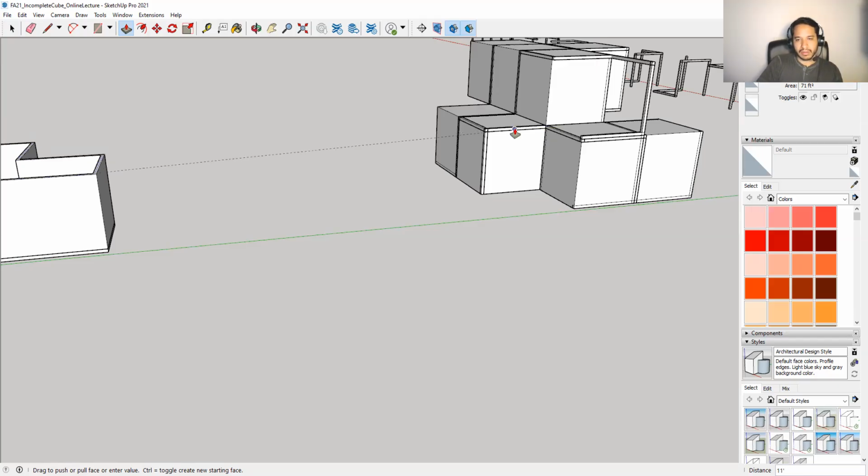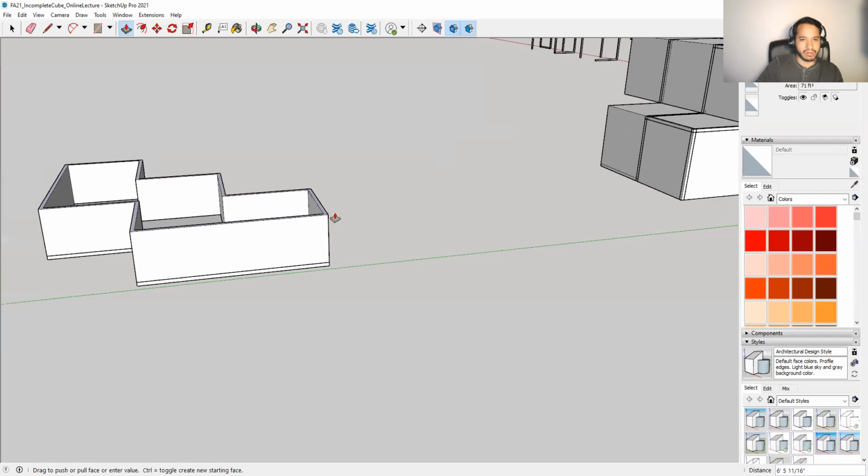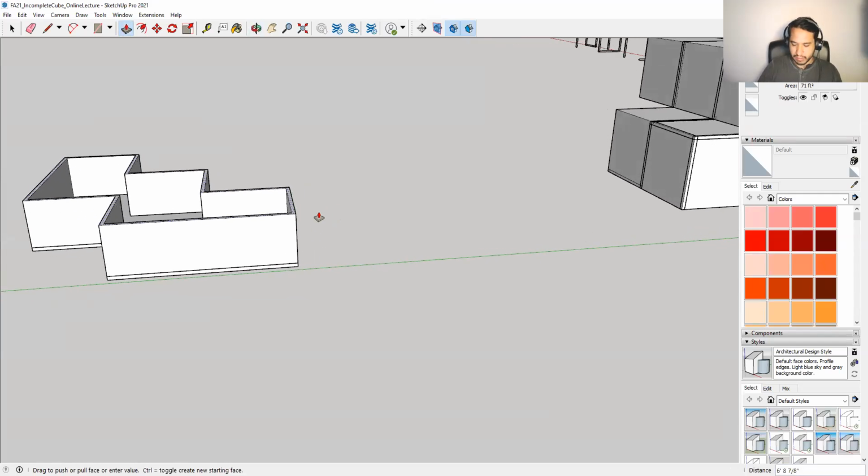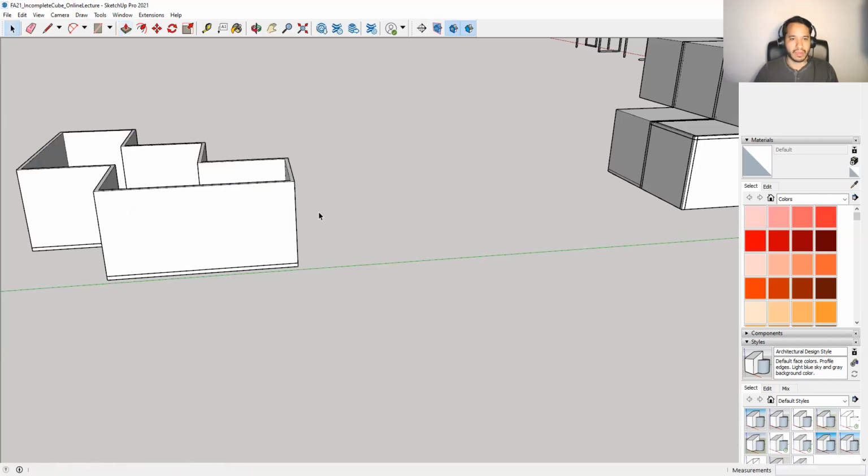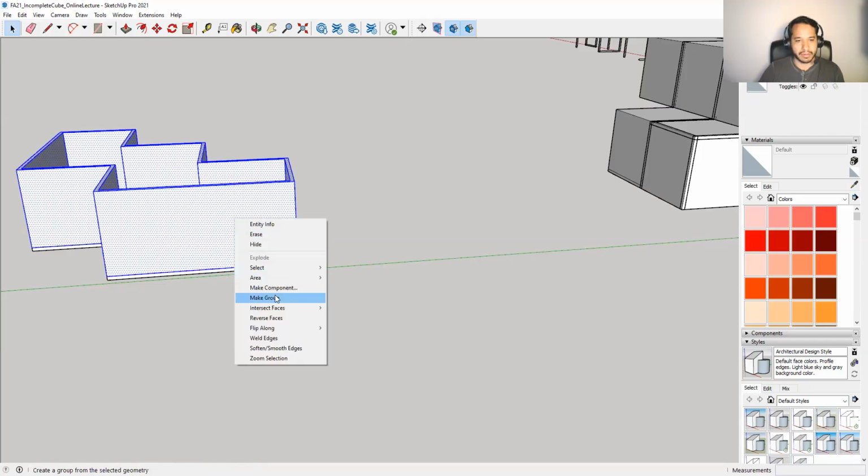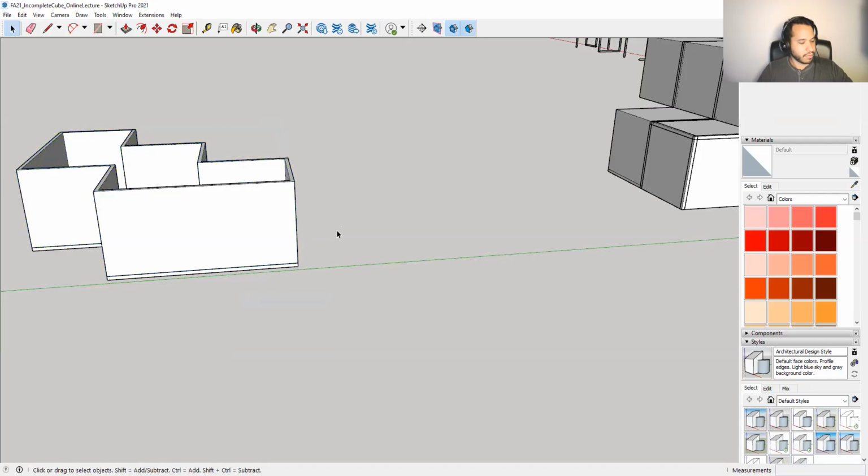And so the roof is going to sit on top of my walls. So if the top of the roof here is 11.6, that means that my walls should really go up 11 feet. So I'm going to select my walls so that they go up 11 feet. Enter. And then again, once we go up, we triple click and make group.